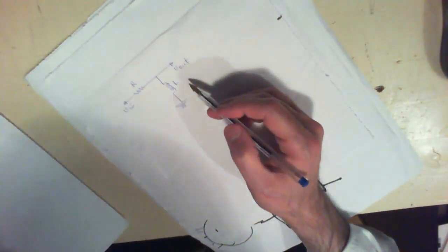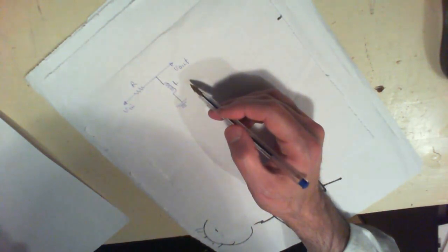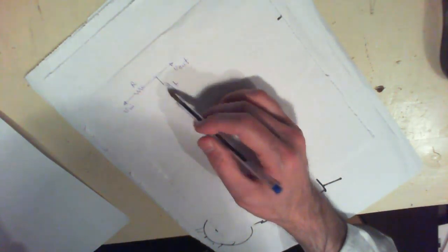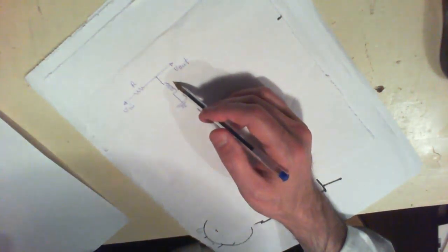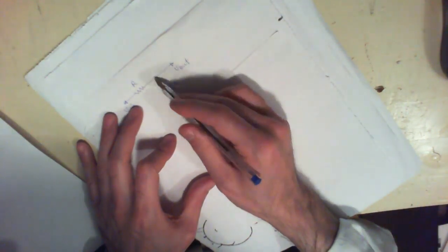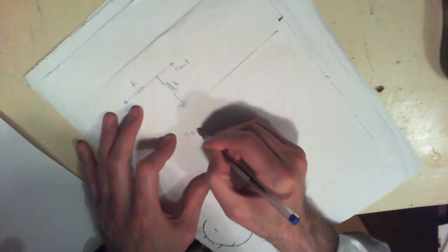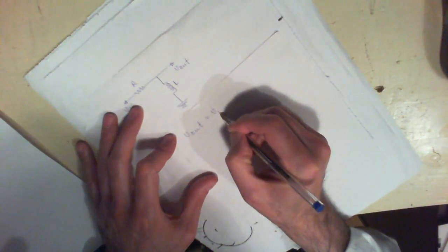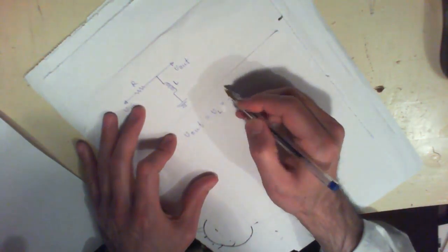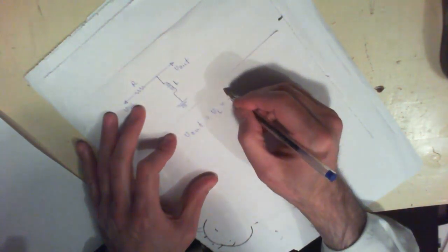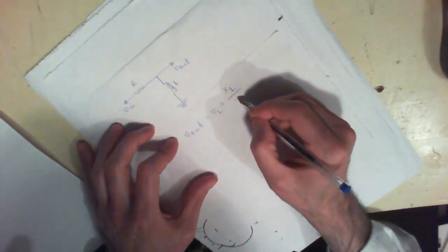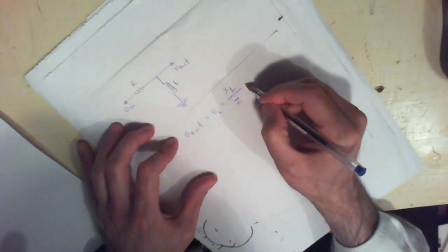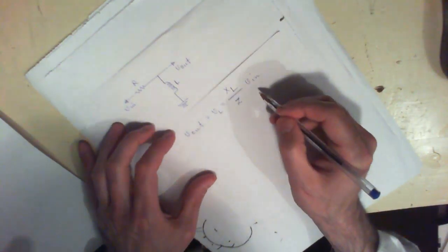Now what happens here is you are actually monitoring the voltage across the inductor, and as we said before, the voltage across this inductor, V of out, which is equal to V of L, is equal to the reactance of this inductor, X of L, divided by the total resistance in this circuit, which is your impedance, times V of in, right?